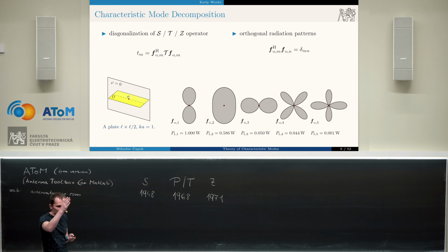So once again, this is why we really like characteristic modes a lot. Just from the visual inspection, you can realize what the building blocks of your scatterer and of its potential electromagnetic behavior are. You can easily isolate modes you like or prefer because you know that their performance is what you need for your application. And also, considering a scattering application, we know from the slide before that this could be an extremely compact representation of your problem.